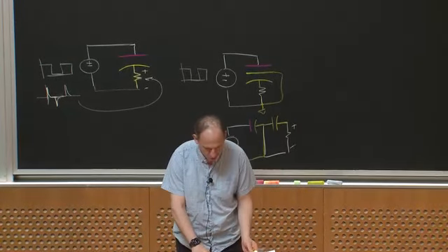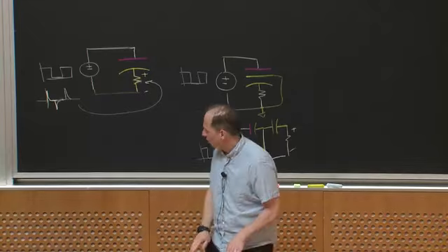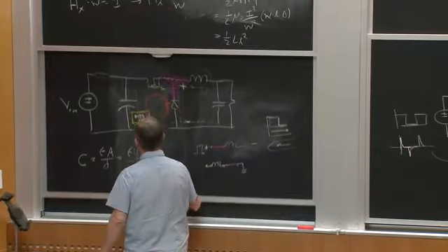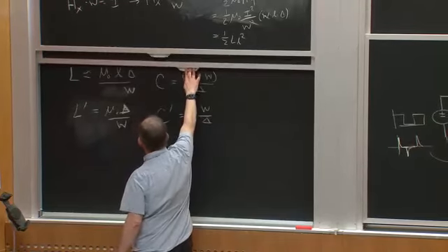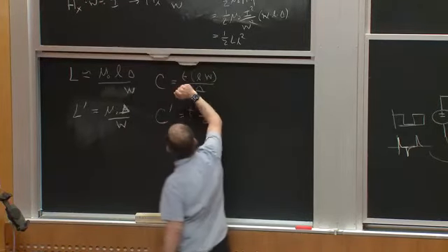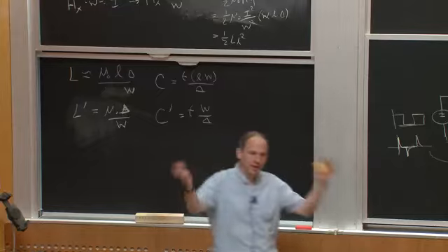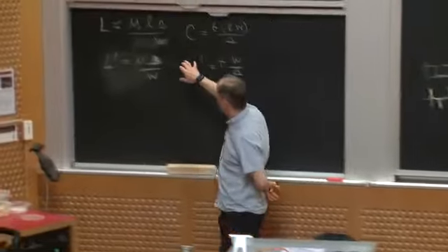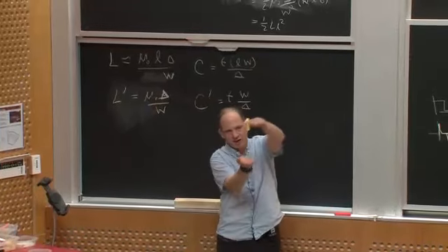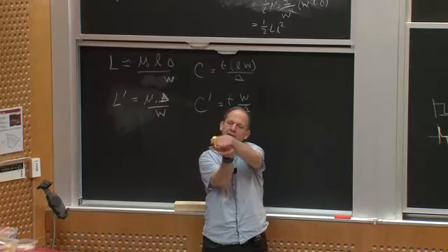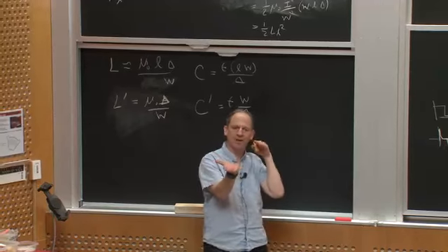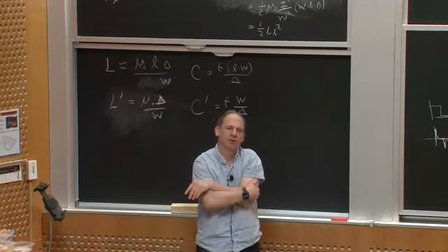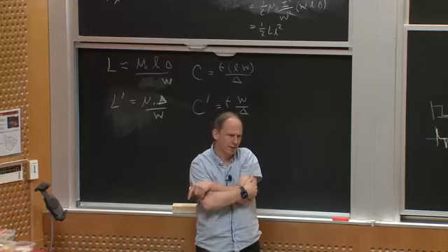I should give you a little warning, right? When I did this approximation and hopefully got the right actual equation here, to get the inductance and the capacitance, in both cases I was neglecting fringing fields, right? So when does this inductance equation really work well? It works well when you have two really wide conductors put close together. So maybe I send my gate drive signal out and I return it right underneath. That becomes a pretty good approximation to the loop inductance you're going to get.